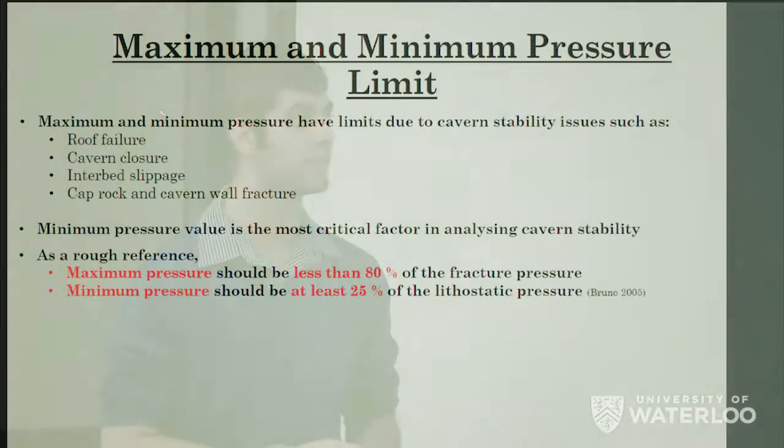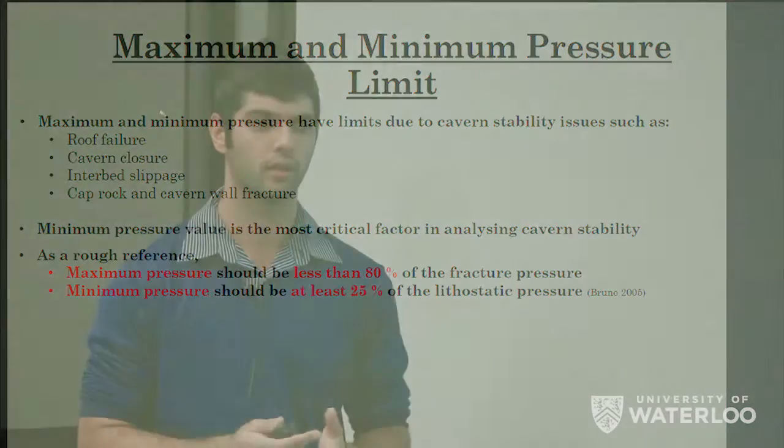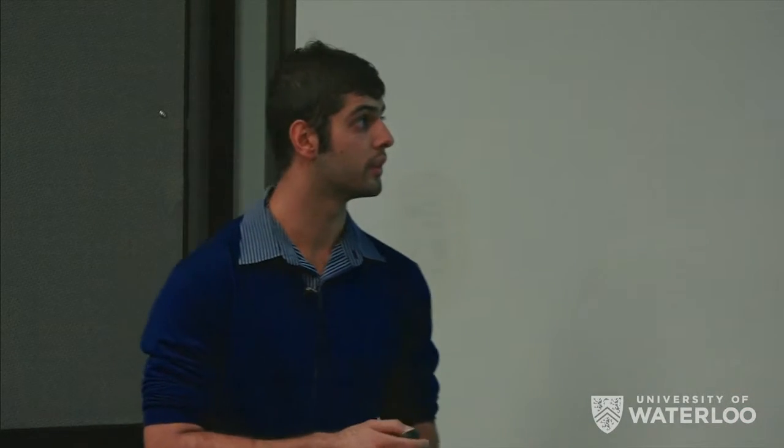As a rough reference, maximum pressure should be less than 80% of the fracture pressure of the cap rock and the salt, and the minimum pressure should be at least 25% of the lithostatic pressure. This is just a rough reference because different government regulations will have different numbers, and different salt areas in the world will have different numbers, and we'll have to do numerical simulation to figure out the exact numbers.